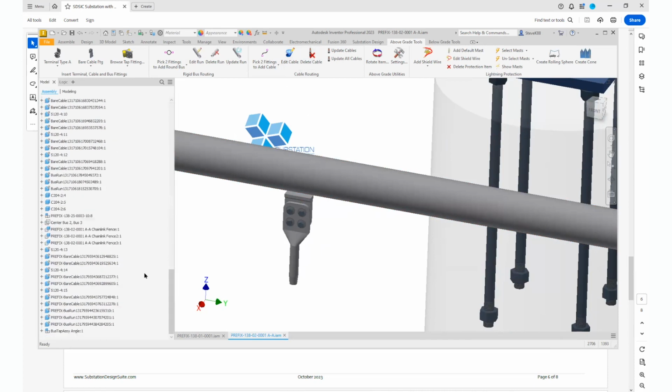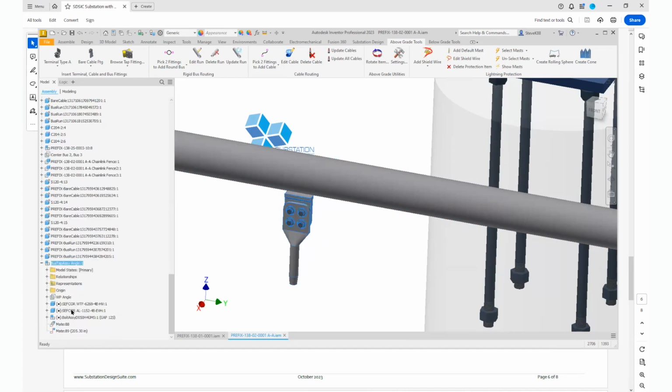Come up here. And here's my bus tap assembly. I'm going to expand it. So this is for a 5-inch. So now it's attached to 5-inch. If you don't know this type of tap, the same tap is good for a multiple range of diameters of pipe. So there I am changing that.